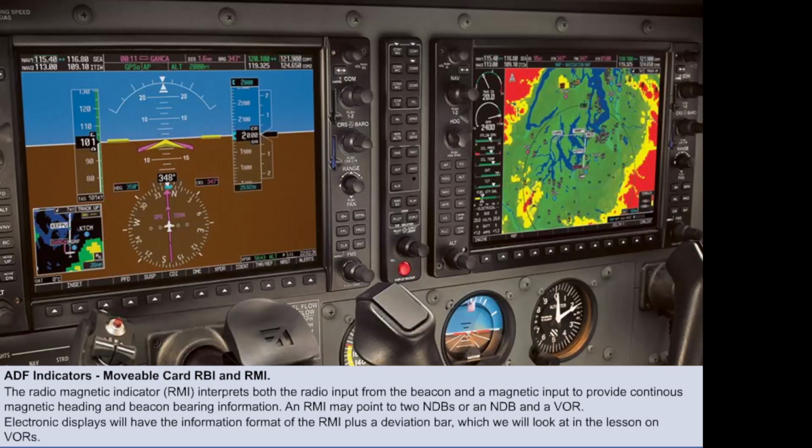Electronic displays are now frequently used, and it is the RMI information which is displayed, but with the additional features of a deviation bar. This represents the track you want to fly on, and it shows how many degrees you are away from this. When the bar is in the center, you are on track.